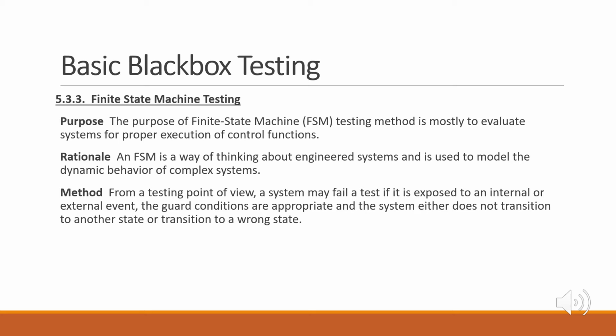An FSM model has a finite number of states and transitions between those states, which occur in response to specific events within the system or inputs to the system. The state of the system represents a situation during system life when it performs some activities or waits for some event. More specifically, when the system is in a given state, it will perform specified activities associated with this state and usually produce specific outputs.